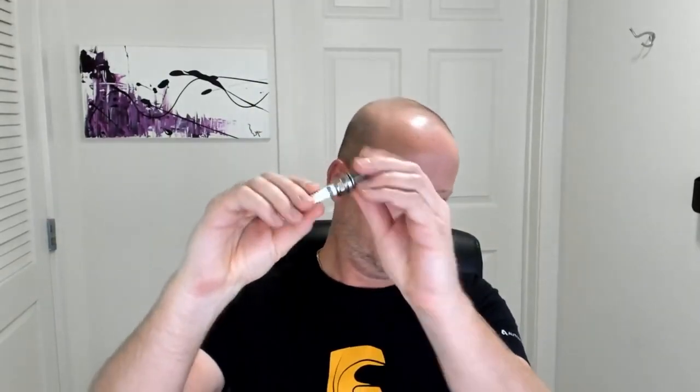So if it's in the machine and we're turning it, actually I got that set backwards. If we're chucking on this side here and we're turning here, and this is all thin over here, if we leave that thin and then mill out here, I'm afraid we're going to get chatter. We've got to cut the thread. So we've got some features to cut here first.